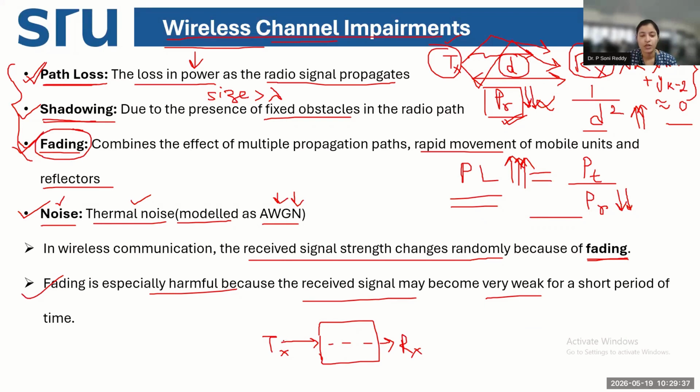When the signal is passing through this wireless propagation channel, because the receiver is hidden behind the big obstacle, the signal will experience multiple reflections and reach the receiver behind the obstacle. When it is experiencing multipath effect or multiple reflections, the amplitude of the signal is reducing and the phase of the signal is also changing.